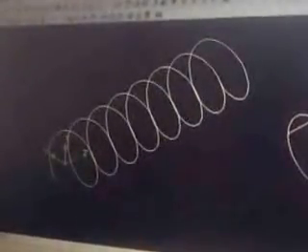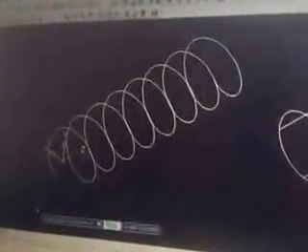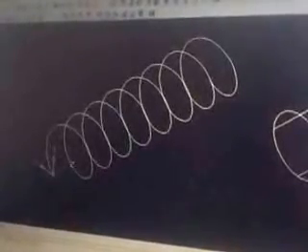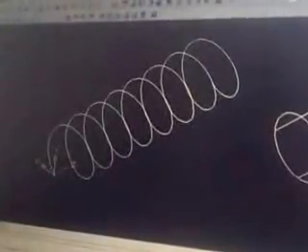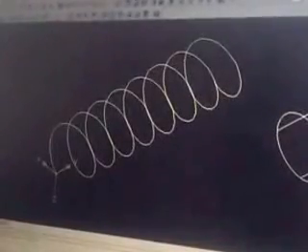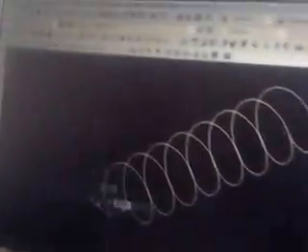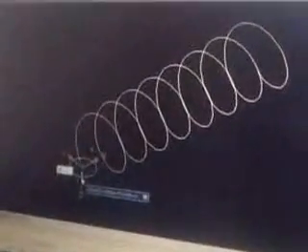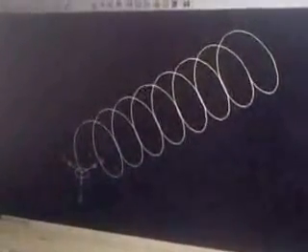Then I move my UCS to this very point of the helix. Then I change my UCS to the position of the y-axis. Now I can draw my circle. Come here, click, and I give the diameter about 0.5.